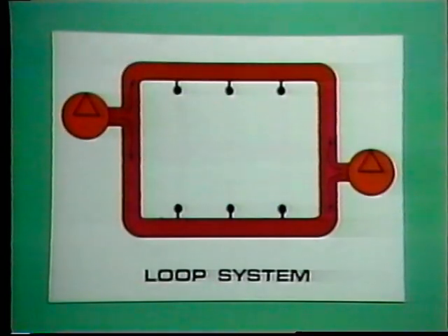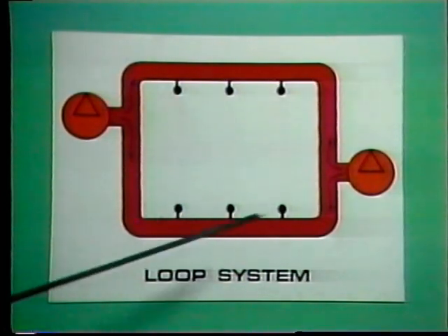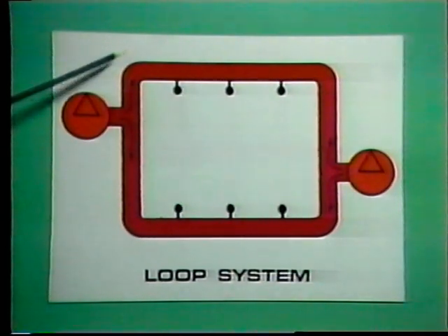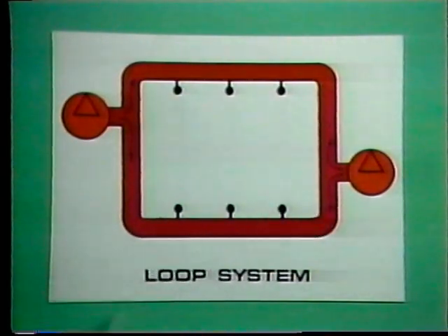The most recommended distribution system is the one shown here. It's called a loop system, and you can see why. It allows for the same size of piping to be used throughout the system, and that gives more equal pressure distribution. If necessary, it's even possible to position air receivers along the loop at points where air demand may be momentarily heavy. So if you did get a sudden peak demand, you'd be able to maintain system pressure and prevent what is called air starvation.